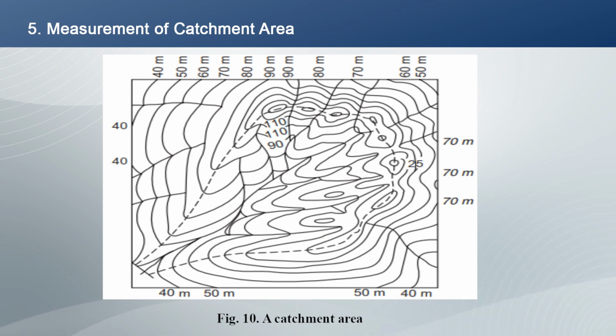During the process of drawing arcs, it may be noted that it cuts the next higher contour at 2 points. Only the point suitable for the proposed alignment, considering the general layout and geological features, is accepted and the other points ignored. During construction, the route of the road is made to follow the contour gradient line so obtained as closely as possible. Fifth is measurement of catchment area.